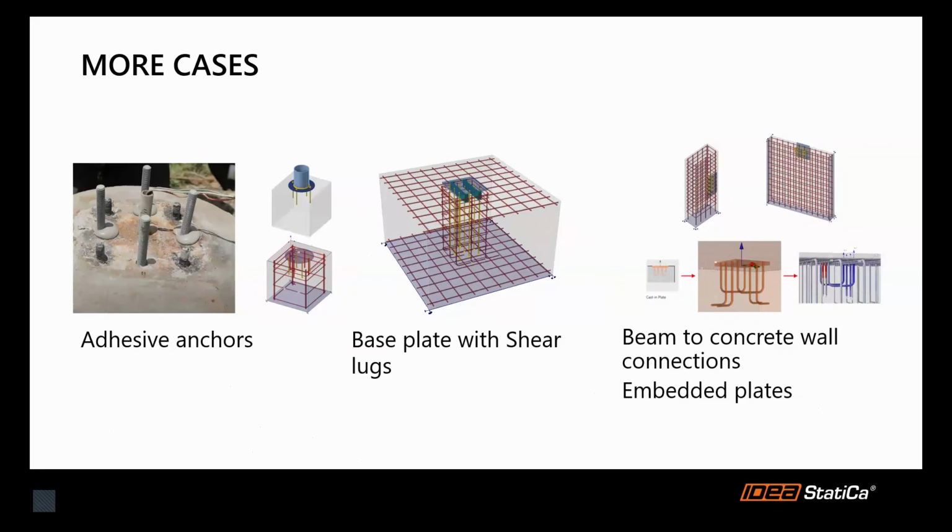If we look at some other cases that we can check within detail, you can use adhesive anchors and add those into your model. Shear lugs, base plates with shear lugs, which I know typically get used specifically for higher shear loads. And then also your beam to concrete wall connections and embed plates.